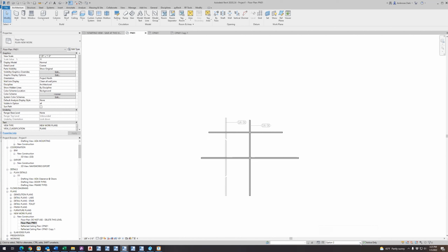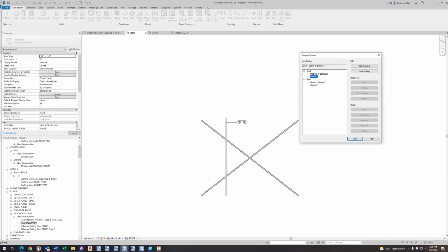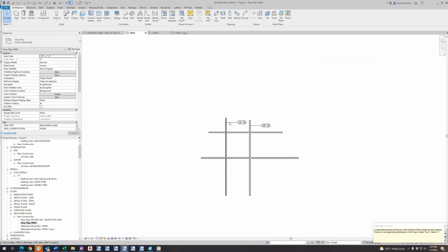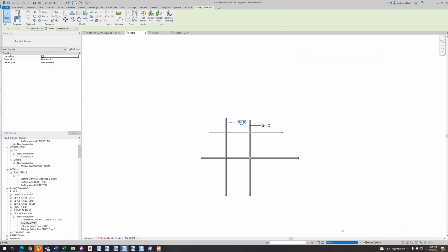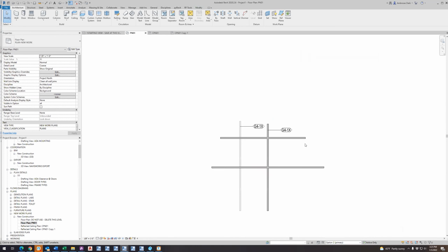Or if you switch primary, that's another thing. Right now, option 1 is primary. You see this tag is dark. If I go and I make this one primary, let me finish editing. If I make this one primary, it will delete this tag. A relationship between elements in the main model and the main model has been deleted. There's no corresponding relationship in duct option 2. So it's saying that tag, I think it was, I might be wrong on that, but when you change primaries, I think you do run the risk of deleting your annotations. So just be aware, if you switch the primary option, you do run the risk of losing your annotations and tags.